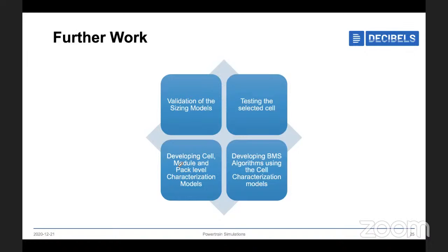Which means here we'll be implementing the driver model also. When we implement the driver model, it will make sure that the vehicle is following the drive cycle, and it will make sure whether the energy, I mean the battery pack size, is sufficient or not. So in that way we can validate the model. Or if not, you can directly go for real-time testing of the vehicle after developing the powertrain simulations.